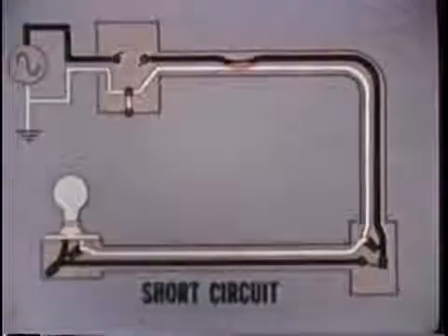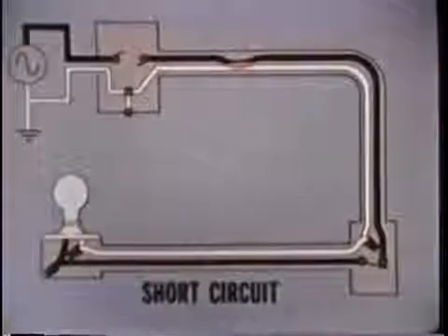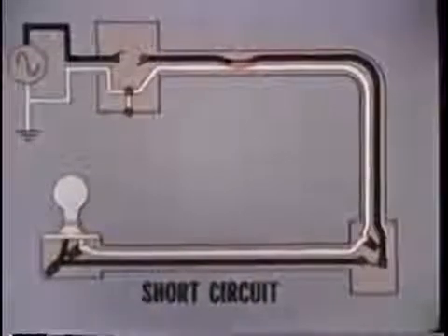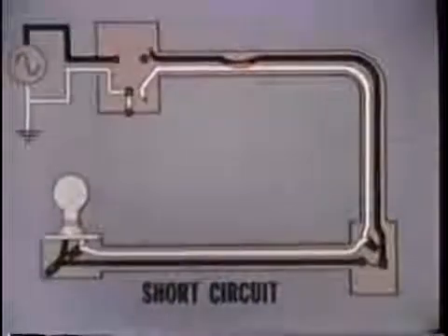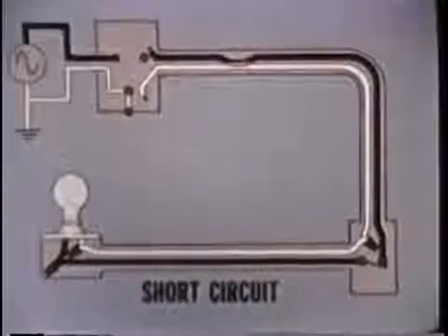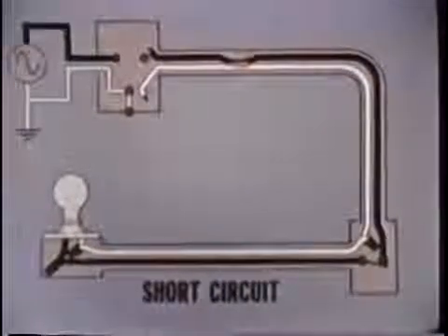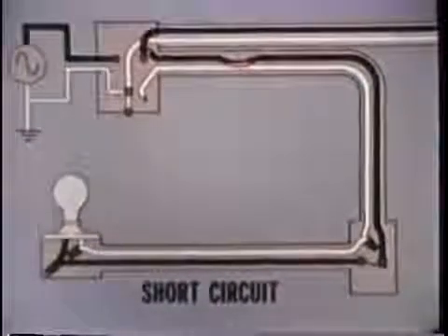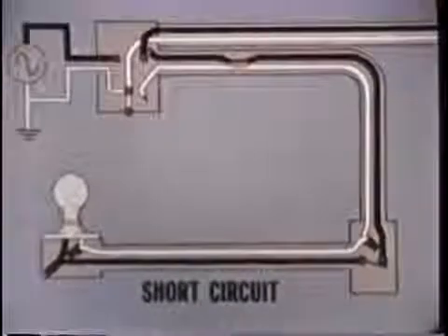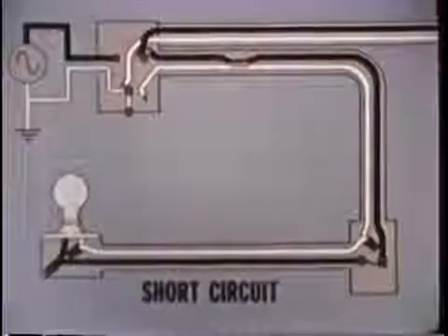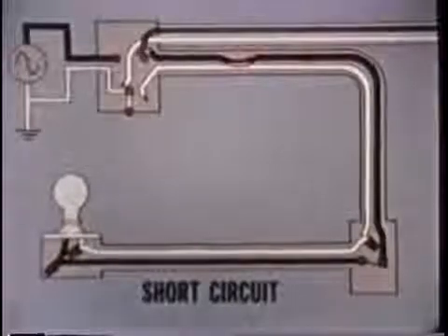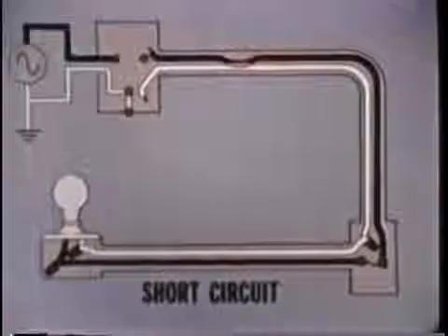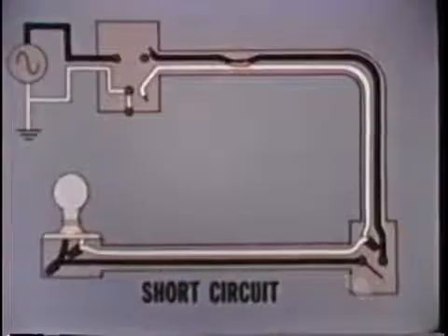The protective device has been set off, indicating that the fault is probably a short circuit or a grounded circuit. To check the wiring safely, disconnect the conductors from the power panel. For the hot conductor, this is normally done by removing the fuse or opening the circuit breaker. However, if more than one circuit is controlled by the fuse or breaker, the conductors must be physically removed from the power connection and separated. Since a short or ground is suspected, remove the other elements of the circuit by opening the switch and removing the bulb.